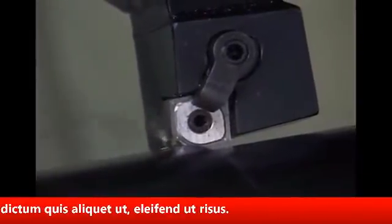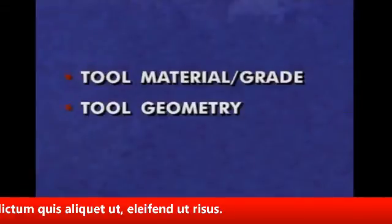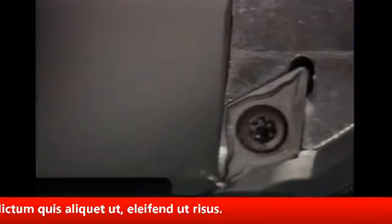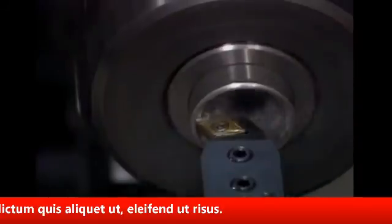Several decisions are required when choosing tools for turning, including the selection of the material or grade, the geometry, and the tool holder design. Just a few basic geometries and carbide grades are used in 75% of turning applications. Tooling decisions for lathe operations